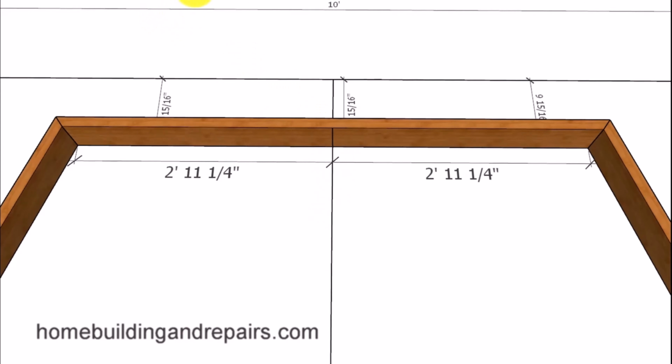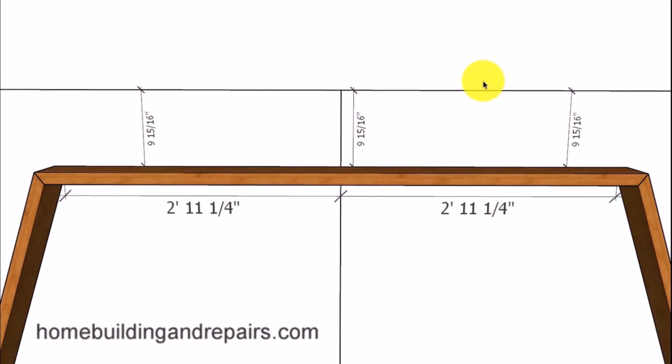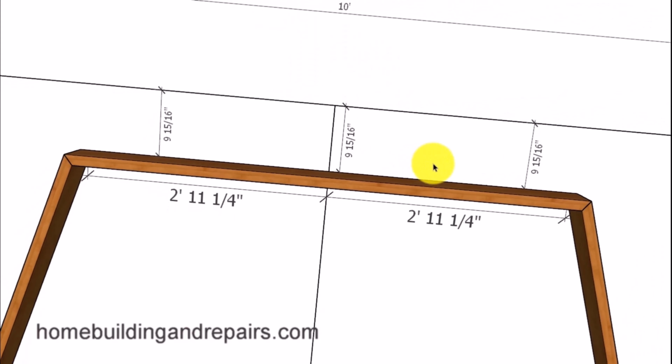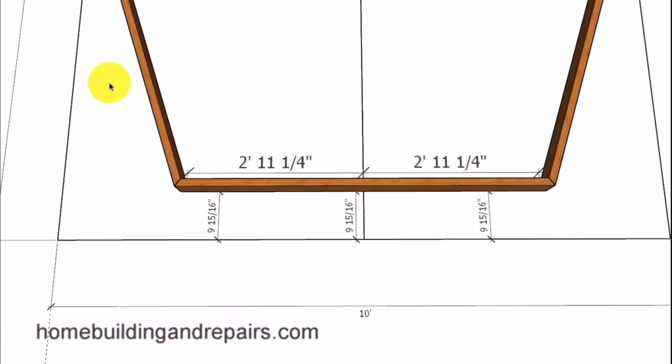However, we would need a parallel line, or like I said before, a string or a form on the outside, creating some type of a square shape that we could measure off of to make sure that this board here is parallel to the line here. So again, the square that we're running around the perimeter here.